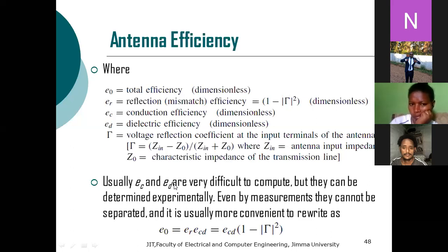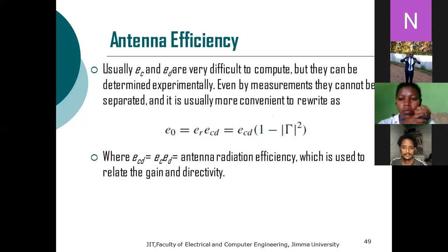So after measurement, we can bring it back into the expression that we have developed, so that we can have an expression for the antenna efficiency in terms of the efficiency measurement data. Then we can again formulate the general efficiency of the radiating element by taking into account the reflection efficiency due to the transmission line. So this is what it looks like.